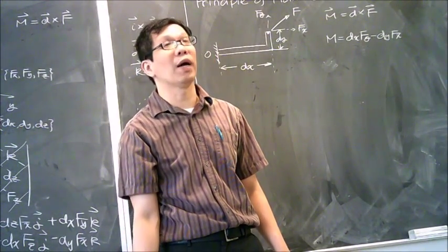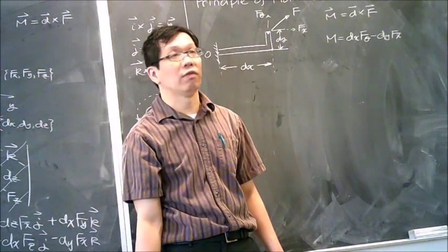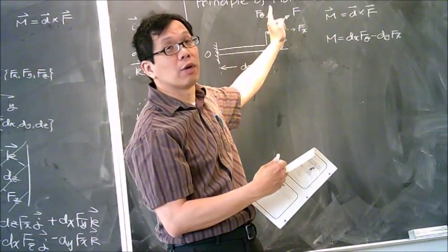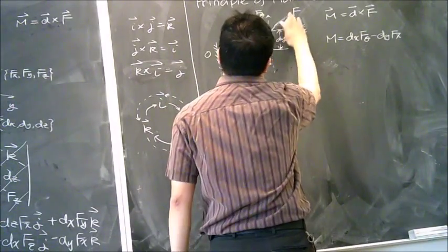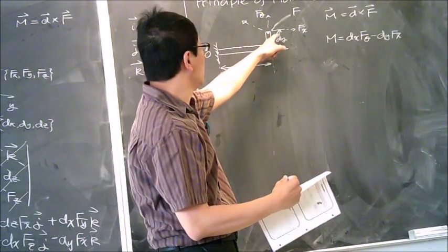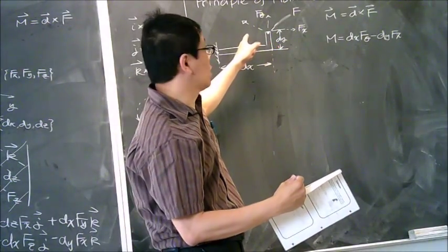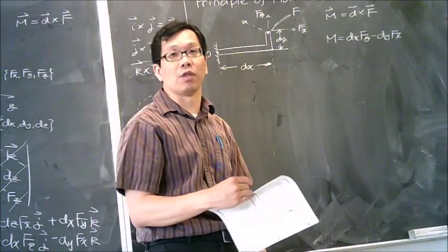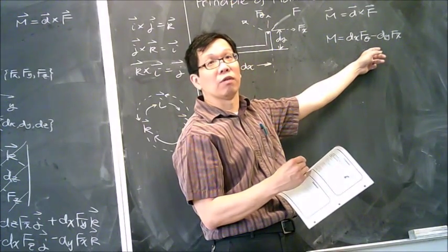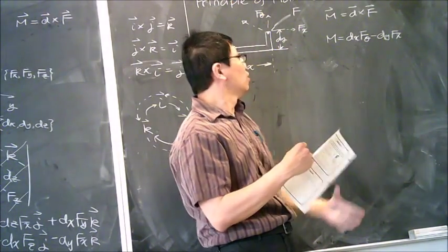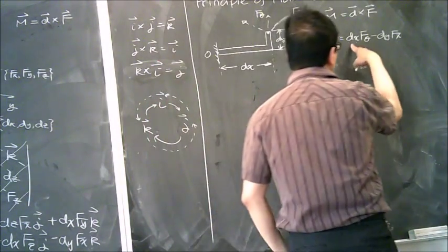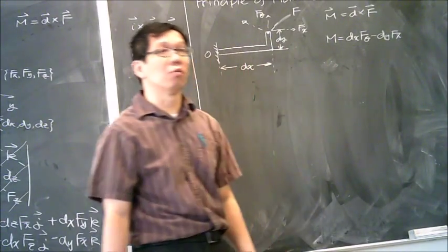So you might wonder, what if my force is not positive when I decouple it into x direction and y direction? Chances are my F is going in this direction, right? So it's going to be a negative force in x direction and still a positive force in y direction. How do I modify this formula over here? The formula itself doesn't really matter because all the numbers we put in this formula, we assume they are positive.